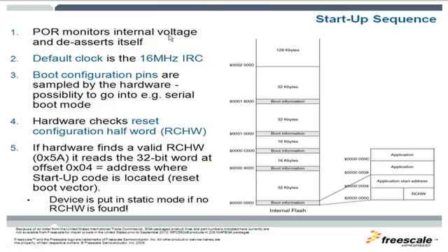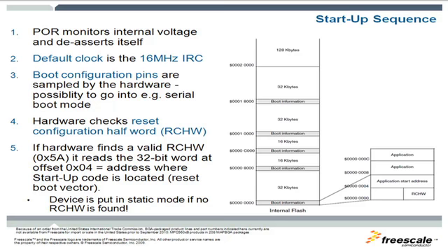And the default clock will start out to be 16 megahertz. This is an internal reference clock. Sometimes we call it the fast internal reference clock. A little sloppy, you can trim it. And then we have boot configuration pins.